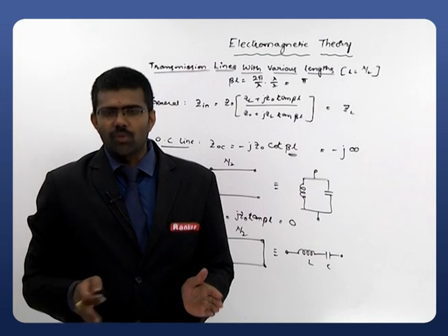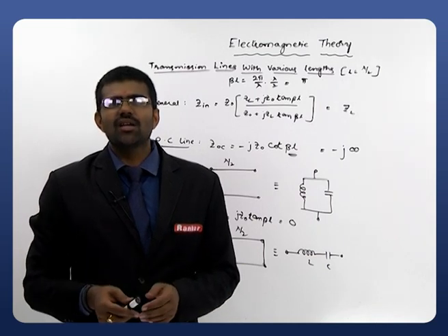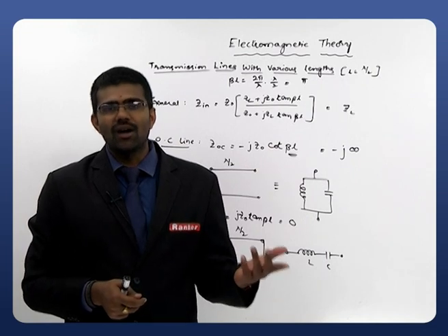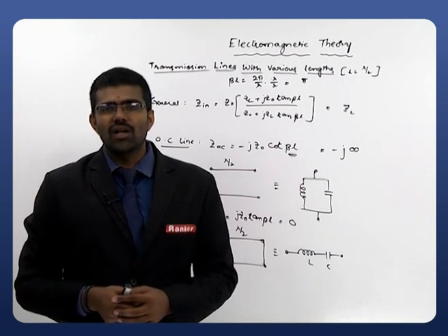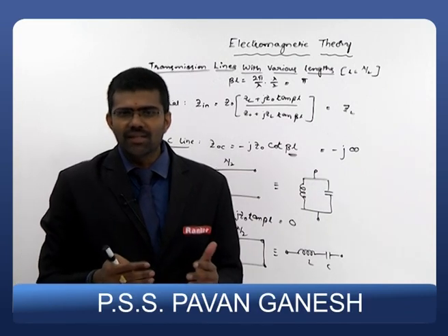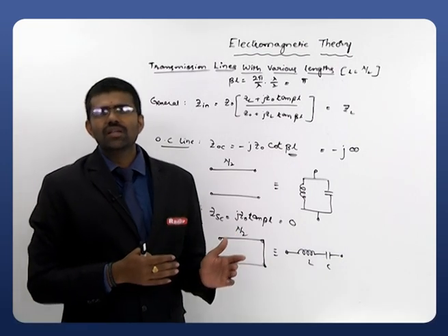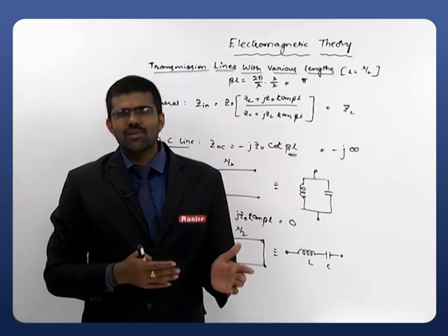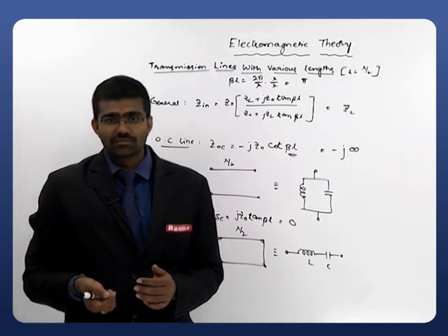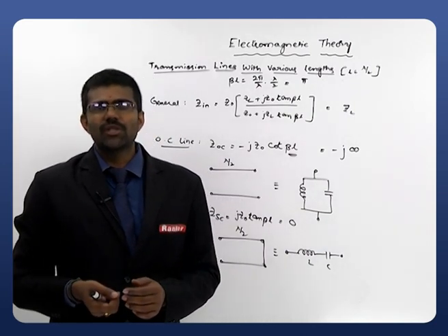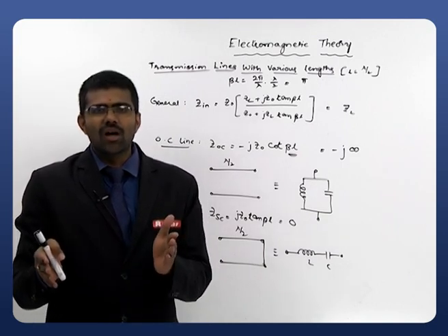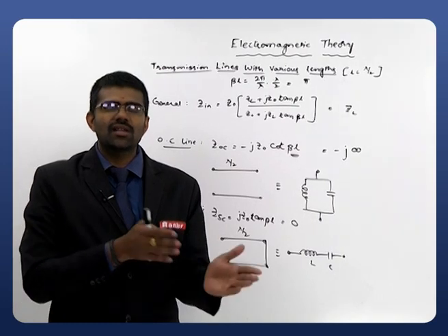Later we can go for the calculation of our transmission line parameters using S parameters, that is, the scattering parameters, or using a special chart called the Smith chart, with which we can calculate different parameters. We calculated our input impedance, reflection coefficient, etc. using our conventional equations. The same parameters can be calculated using a special graph called the Smith chart. So in our next session we are going to observe what that chart is and how different parameters will be calculated using another parameters called as